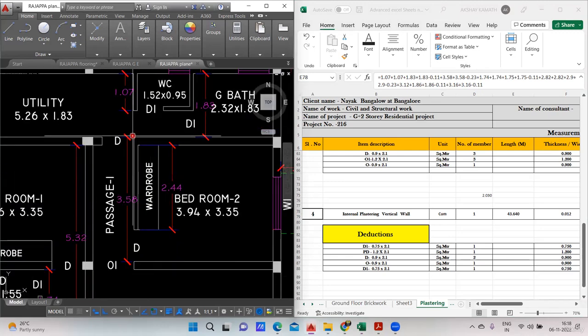So after that, you come here. After that, see, again, same here also. Okay, again, door is coming. So I'll take, you cannot take plastering up to here. You have to take complete length. Then you deduct the door part from that so that you get the total plastering.